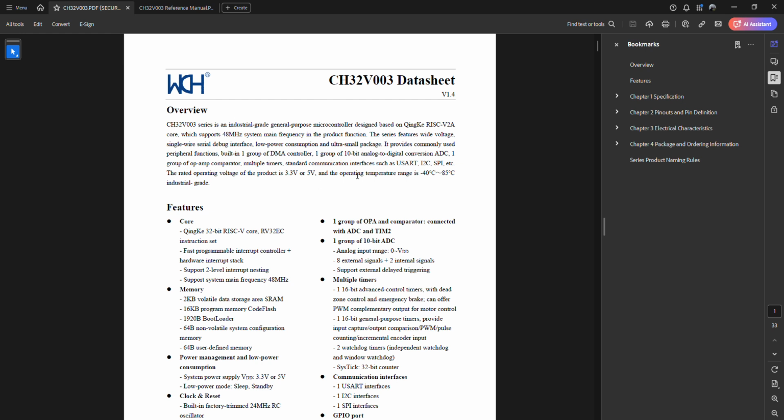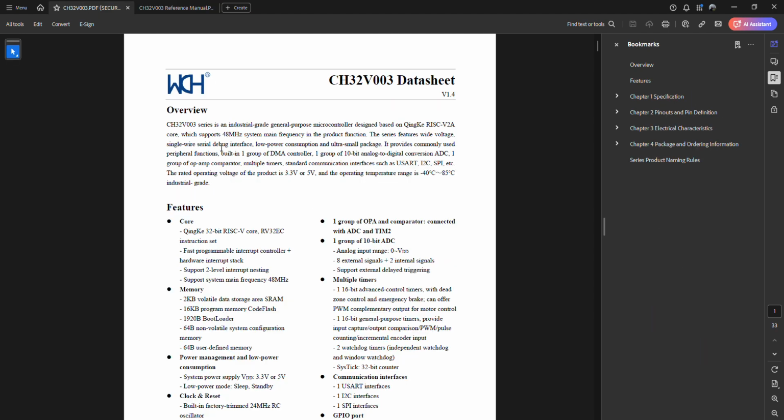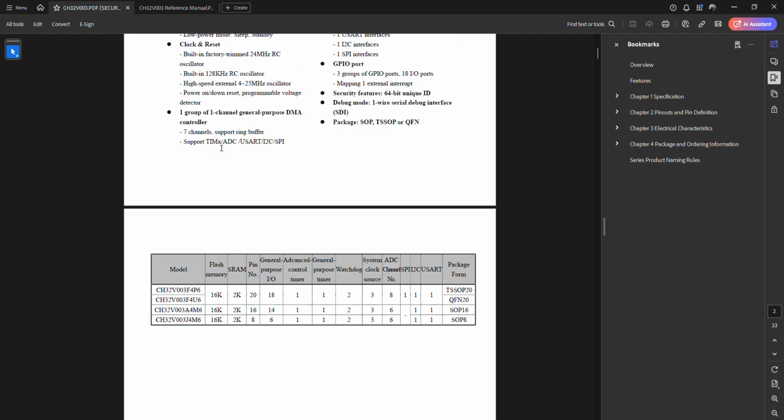It usually shows the specifications, the pinouts, the package type, electrical properties and other things, which are, in short, very technical and usually deal with numbers. The reference manual is actually the literature that explains what each peripheral does and how it can be programmed, what features they have, what can be done and what cannot be done. These two sets of documents will only be needed if we want to get down to the deep.